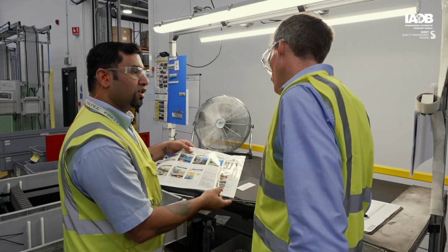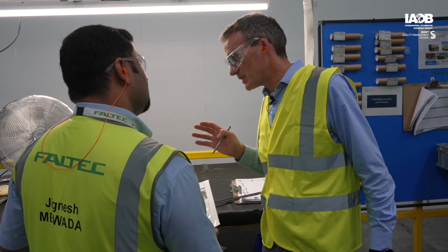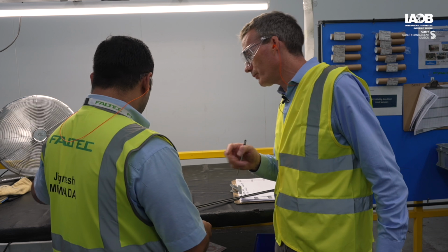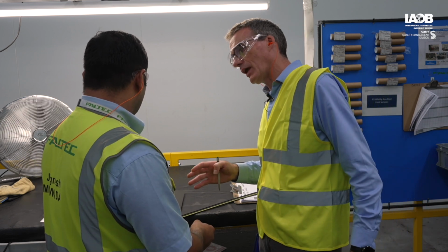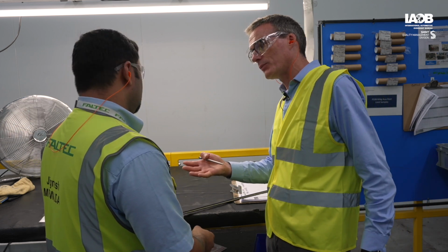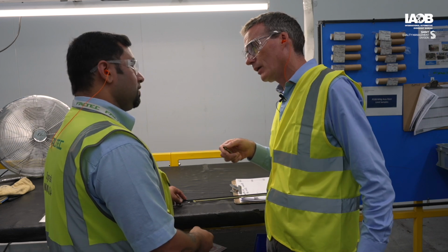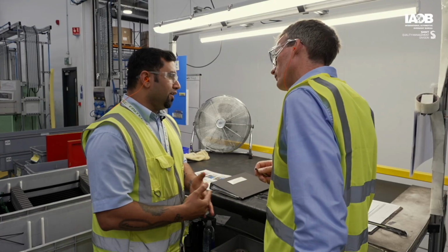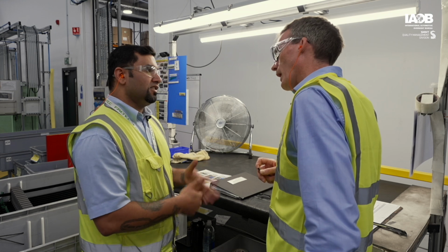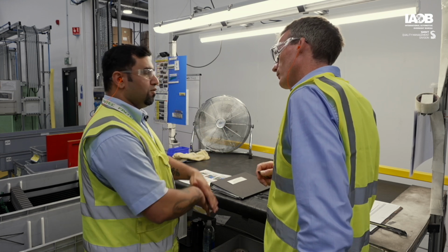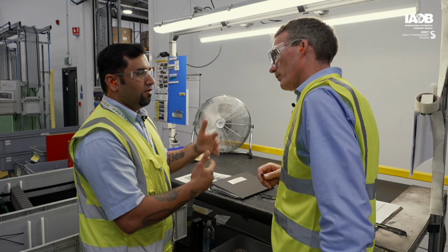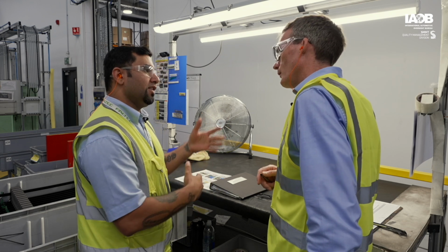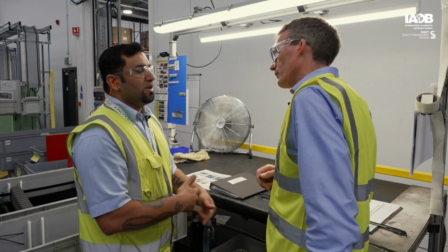So it's a known concern. And if we talk about the end cap detachment with the notification that you had yesterday, would you create a specific quality alert for that? Yes. First of all, we raise this concern like a CIR, concern investigation report, which will be completed by a quality engineer, like a 5 whys and Ishikawa and everything. Get done by that, and on the basis of that, we'll have permanent countermeasures.